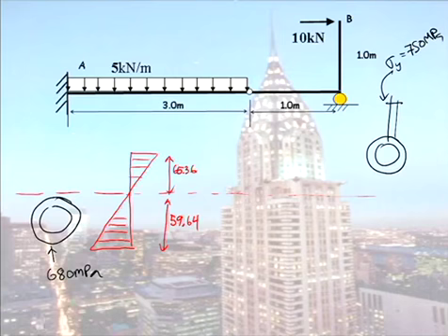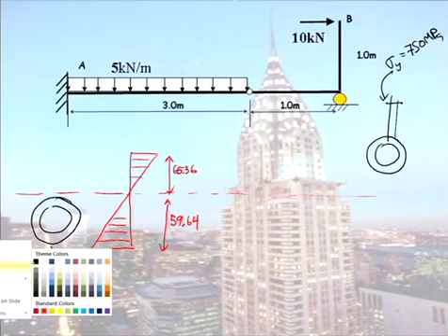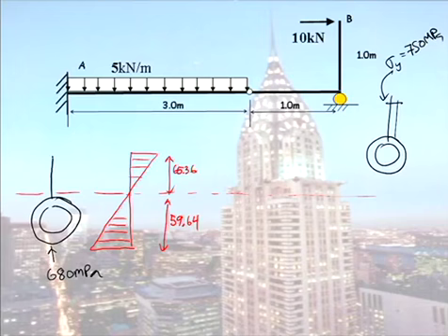And I'll just do that quickly while you're taking it all in by making this a lot taller. So now, does that stress at the top look bigger? So are the top and the bottom of the section going to reach the yield stress at the same time? No. Because this distance is bigger, the 65, you know that the stress at the top will be greater than the stress at the bottom.